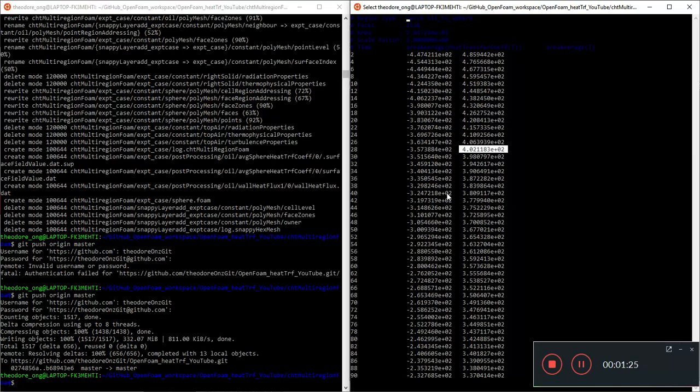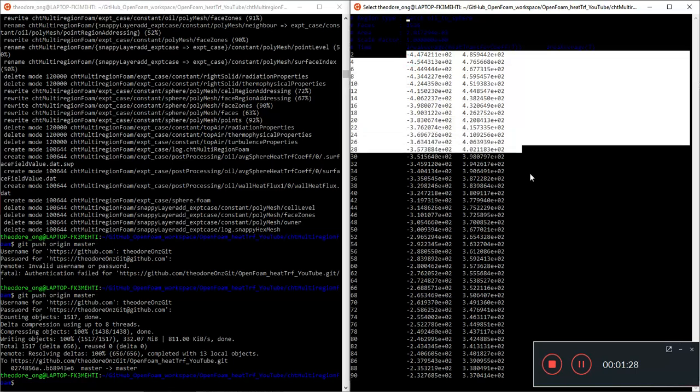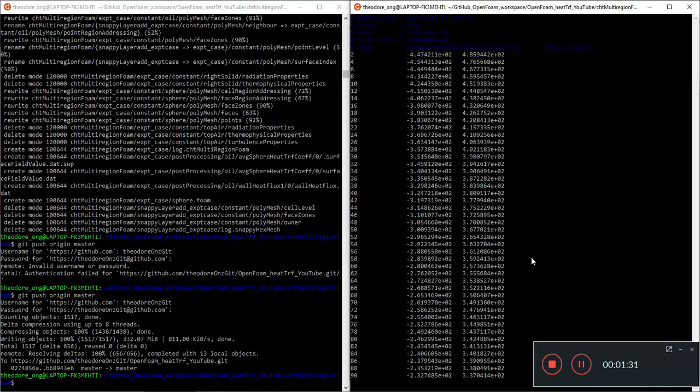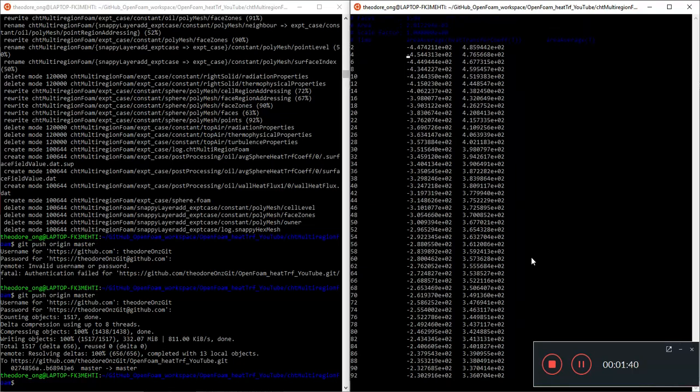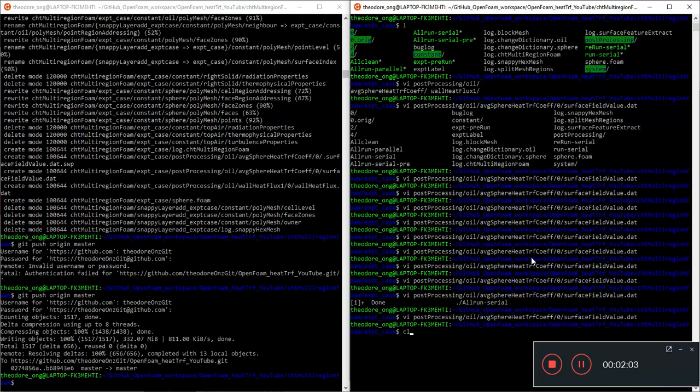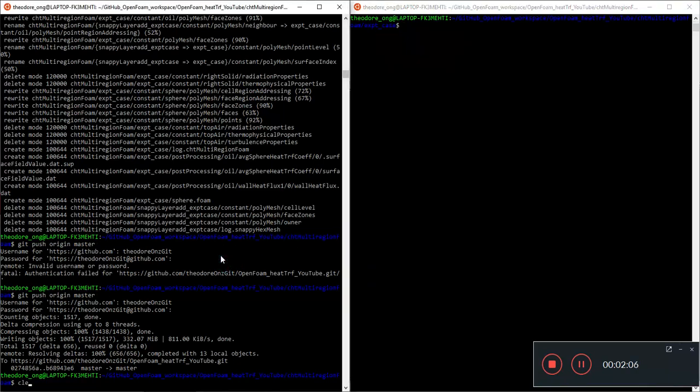It looks like the heat transfer coefficient has jumped several fold and continues to be over 100 throughout this simulation. This is a good sign, because that's definitely closer to our empirical correlations than what we had before. What we had before was a very underestimated Nusselt number compared to the Rayleigh number. This time, instead of comparing to the Rayleigh number, I'll compare it with temperature. It will maybe be a more consistent way of doing things. But let me just show you the